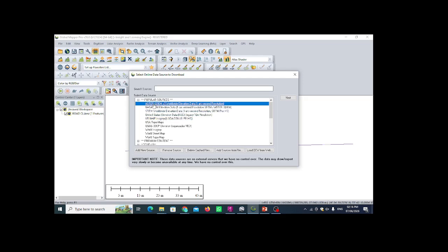But in most cases, for popular elevation data, I use SRTM worldwide reference data. If you select this as per our zone, it will give a good result. So make sure that you use SRTM. If you are not using SRTM and you use ASTER, then it is also not any problem.